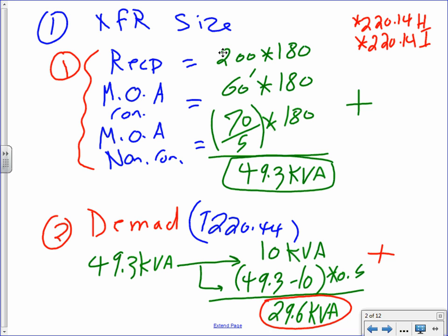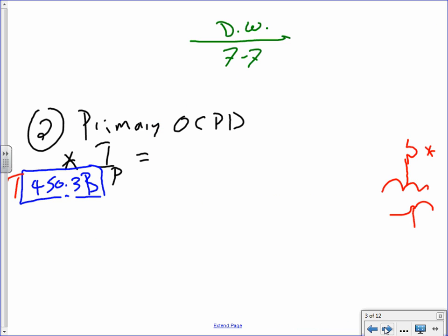What they did here, guys, in this table, two things. They gave you the kVA size of the transformers, as well as the full load current at certain voltages. So, Zach, does it matter if these voltages are primary or secondary? It doesn't really matter. In our case, guys, 99% of the time, you're going to be primary 480 and secondary 208. Okay, so let's go size my transformer, my friends.